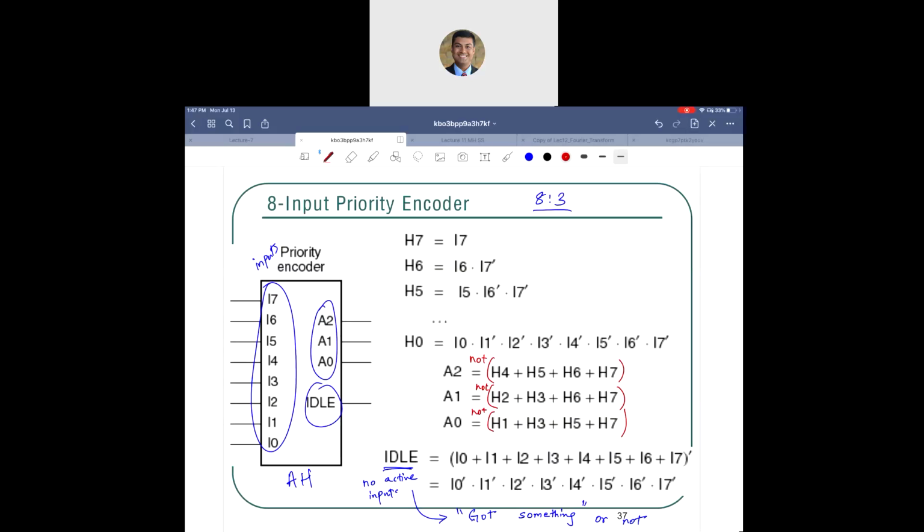Let's see. Kevin says, do we have to do all of these tasks within one? No, no, no. So Kevin, I would recommend you trying to finish task one, and then task two, and then task three. That just keeps you moving in terms of your design, right? So you can do it in the same project, but have three different design sources with probably three different XDC files. And then depending on which one you are trying to get checked off for, you can remove the design sources and the XDC file of one task and then bring in the other ones.